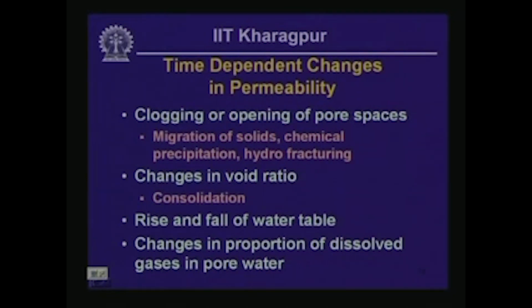Fourth point is changes in proportion of dissolved gases in pore water. That also might actually lead to a time dependent change in permeability, because dissolved gases tend to alter the viscosity property of the pore fluid. As a result, permeability changes depending on the amount of dissolved gases in pore water.